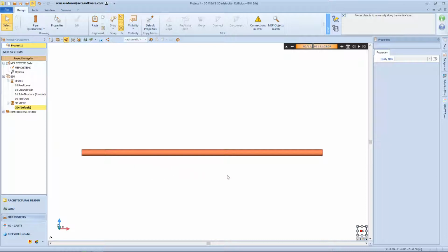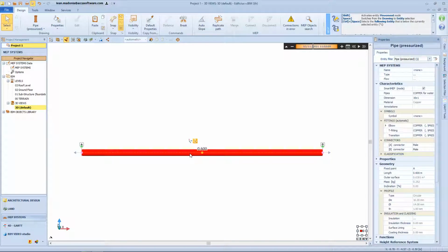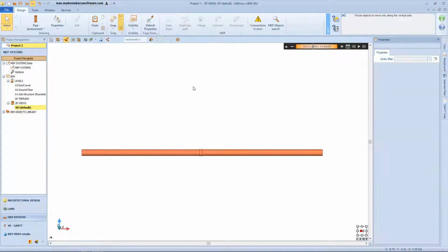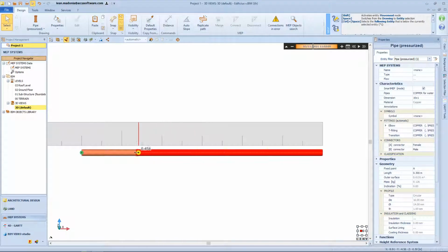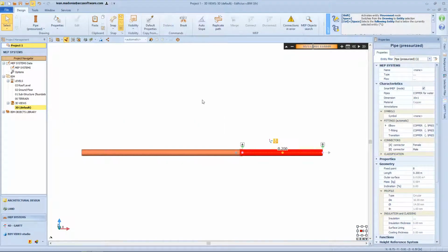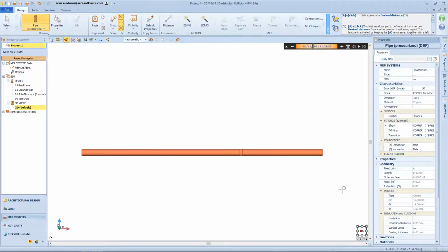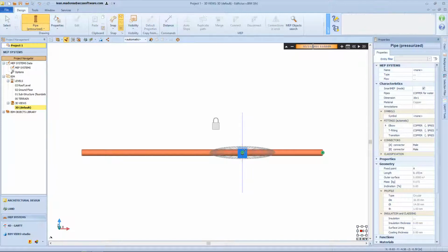of the modeling. If a pipe has already been modeled, but you want to connect a new pipe to it using a T-fitting, you must first create a connection at the connection node. At this point it is necessary to model the branch pipe. If the profile has the same shape and dimensions as the main pipe, the fitting is modeled directly. With the tube entity active, position the mouse cursor at the connection and, when the yellow snap appears which identifies the presence of a connection, you can click to create the branch.